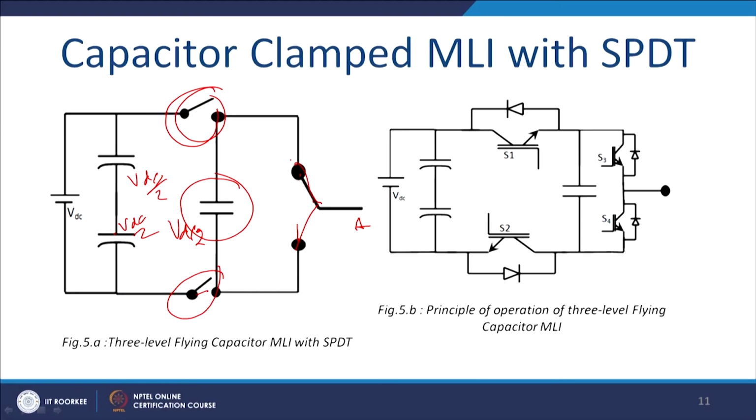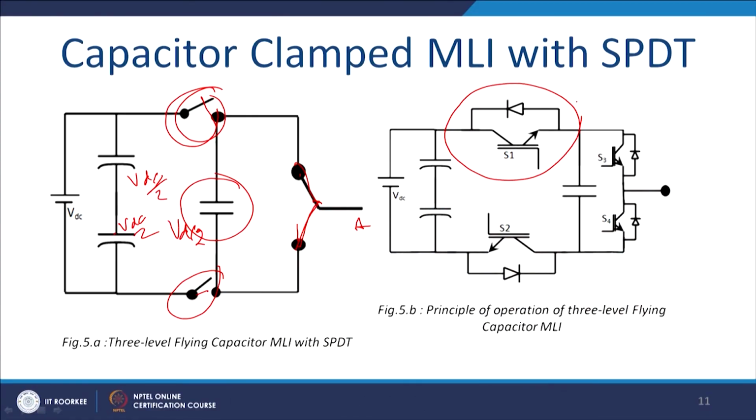So, in that way you can generate multiple states of the voltages, and here this disadvantage is not there because you are controlling the voltage actively. But one of the disadvantages is the complexity of the circuit, which I am coming to later. So, how do you realize it with switches? Essentially, this can be realized by these switches, because the current is required to be bidirectional.